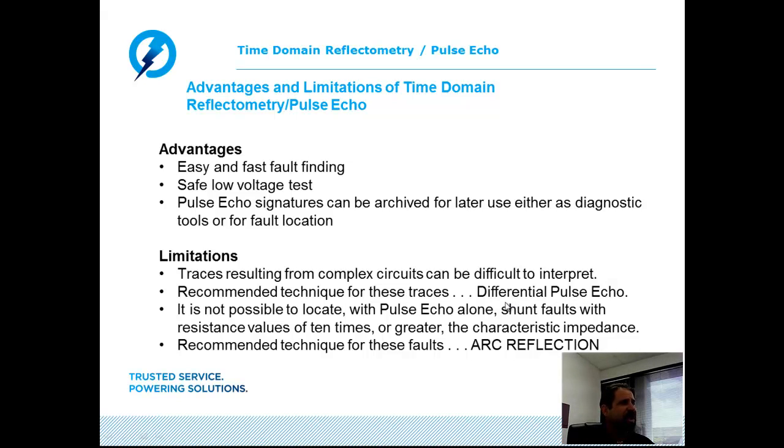Basically, take a picture of a good cable phase and then take a picture of the faulted cable phase. Everything that is common, all the areas where they share common T connections, Y connections, transitions, etc., all these images will be the same. So we take the two data points from these two waveforms and we cancel them.